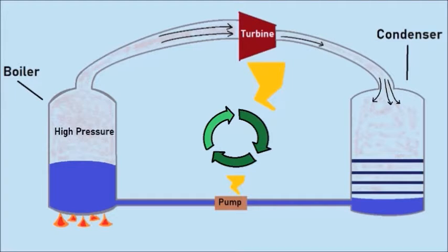Cooling water is moved through pipes, allowing hot steam to condense on the pipes. Because the steam condenses onto the pipes, the pressure inside the condenser stays low. The pressure stays low because steam is not allowed to build up in the condenser, as it condenses down into water when it hits the cold pipes.